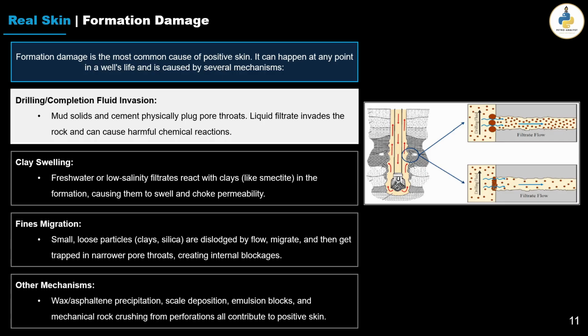This happens during the drilling or the completion. This formation damage or skin can happen at any point in the well's life and can be caused by several mechanisms. One of them is the drilling and completion fluid invasion.